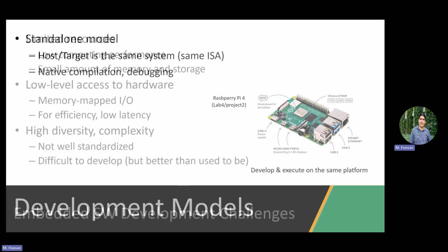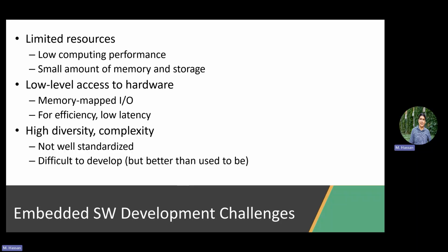So thank you. Some other thing is that in an embedded system, you in fact most of the time have lower-level access to the hardware, right? If you look at your programming experience in 241, you're interacting directly with the hardware, right? Sometimes, for example, to enable an interrupt or to enable a GPIO, you go to a particular register in memory and then mask a certain bit to make it an input port or an output port, right?